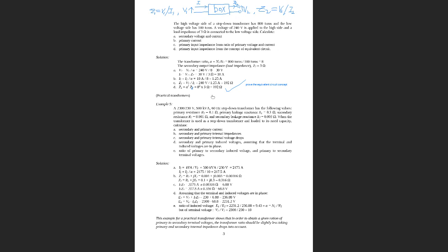Actually, this is applicable to any kind of equipment, any kind of system, 2-terminal or 4-terminal systems. You have input-output impedance issues. In practice, you may sometimes use machines to measure some things, but the machines have their own input impedance, and the other instruments have output impedance. If the output impedance of a machine is not matched with the input impedance of another instrument, there will be reflections of the energy between the two.